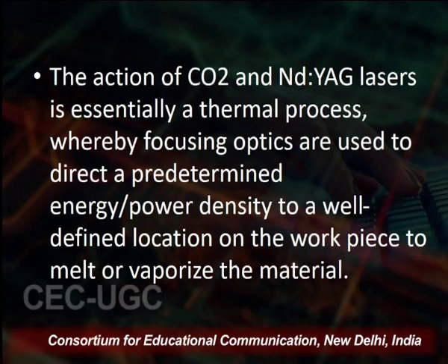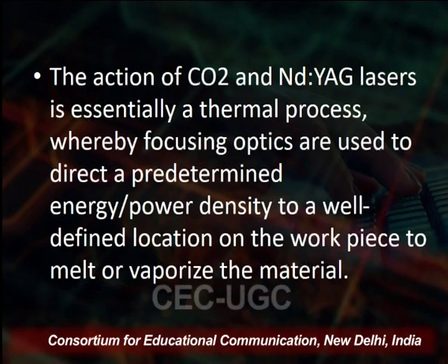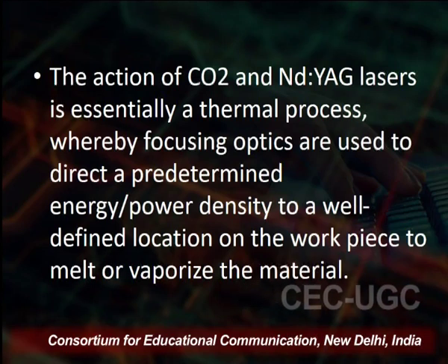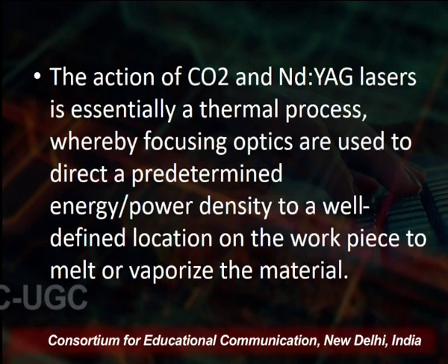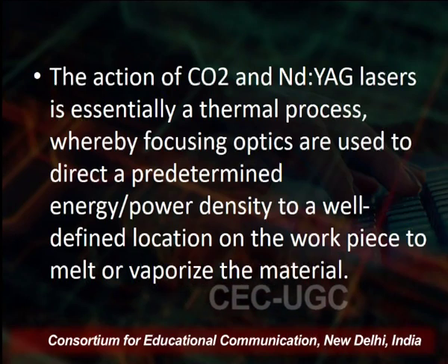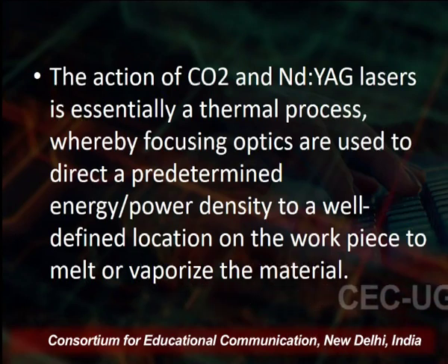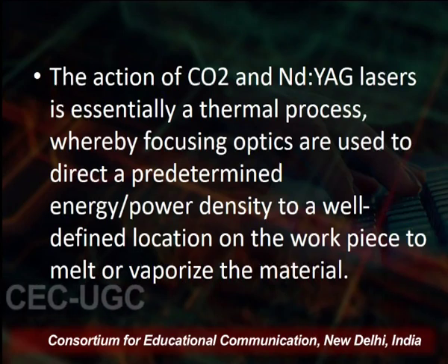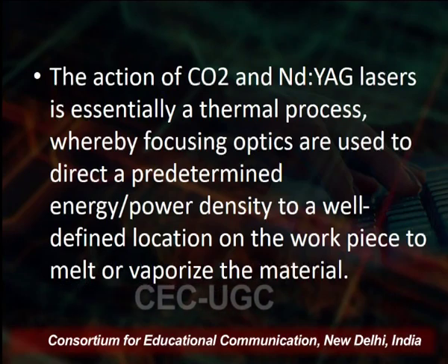The action of a CO2 and an Nd YAG laser is essentially a thermal process. The focusing optics are used to direct predetermined energy, power, as well as density to well-defined locations on the workpiece to melt and vaporize the material.